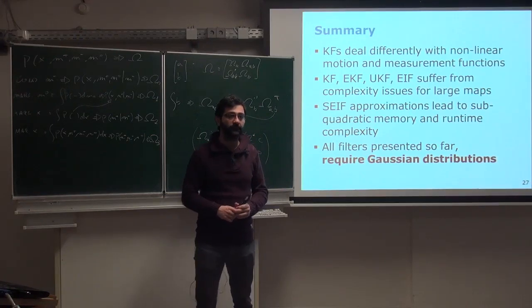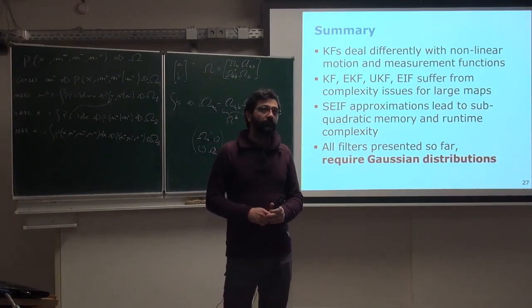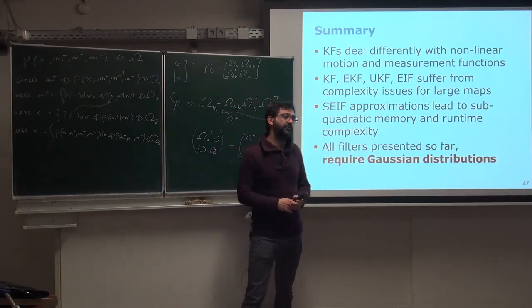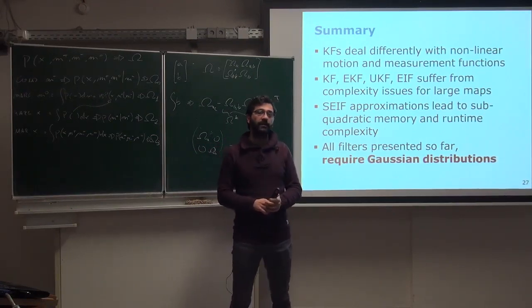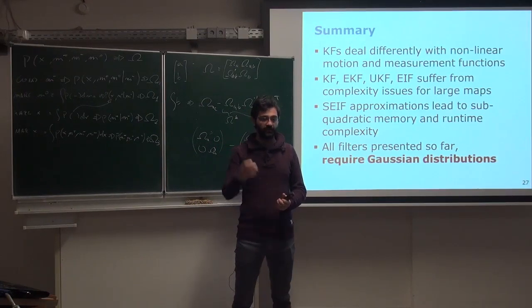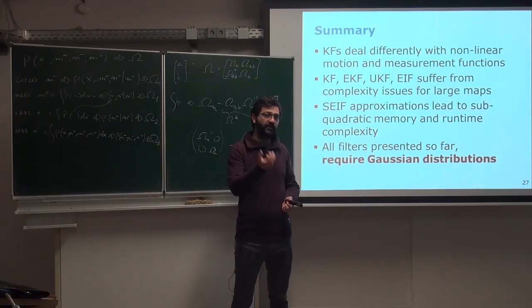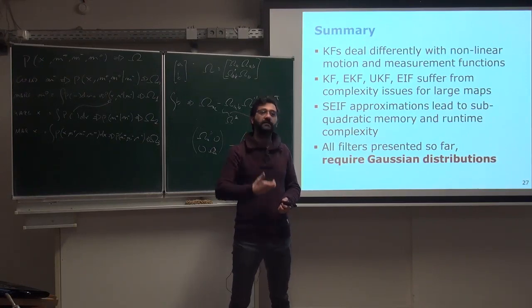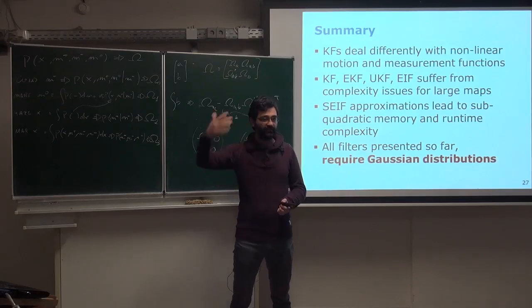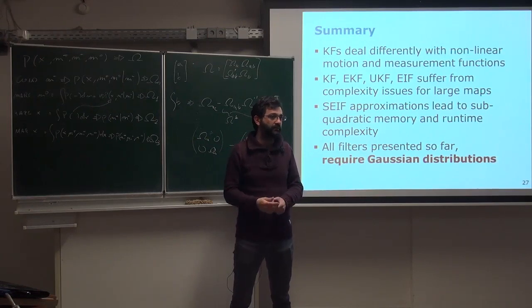So those filters are for unimodal cases, right? Yeah, so those filters are mainly for the unimodal case, and they require as input a unimodal noise, and if you don't have a unimodal noise, you need to come up with something that somehow represents it. But also in terms of belief, they always express one mode in the belief distribution. So they will commit to one solution, to one mode. And there's no guarantee if you really have a multimodal distribution that this will be the correct one. There might be a suboptimal one.